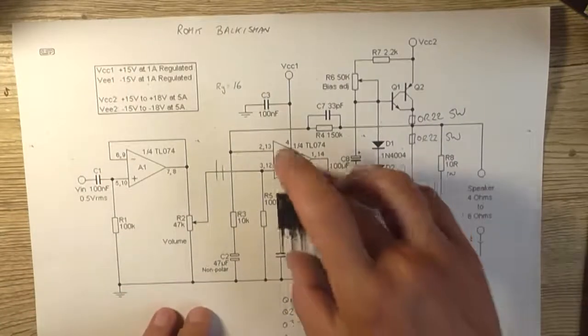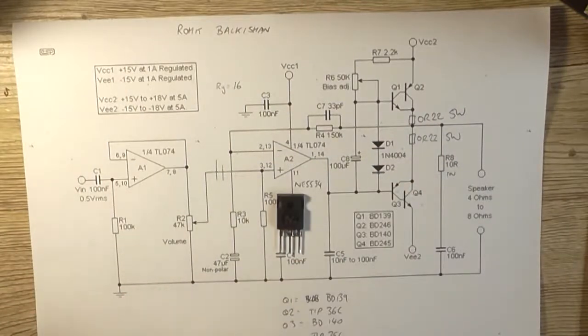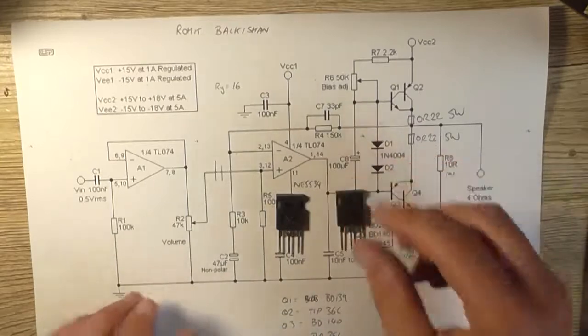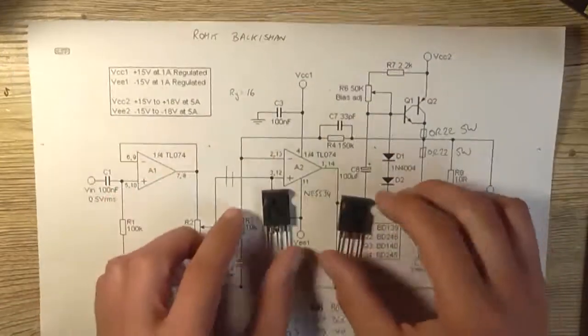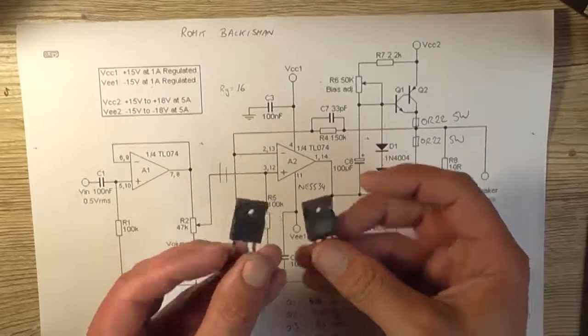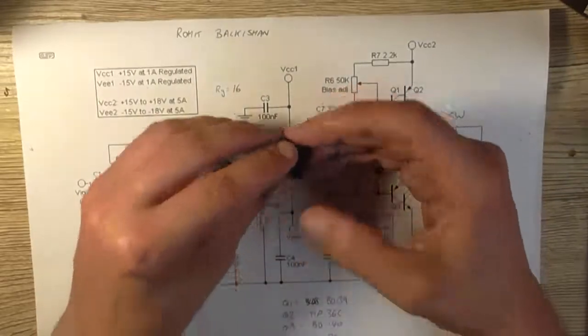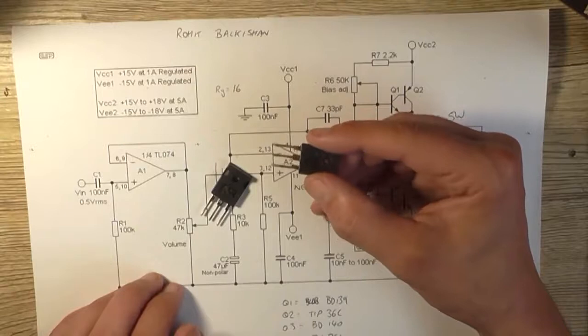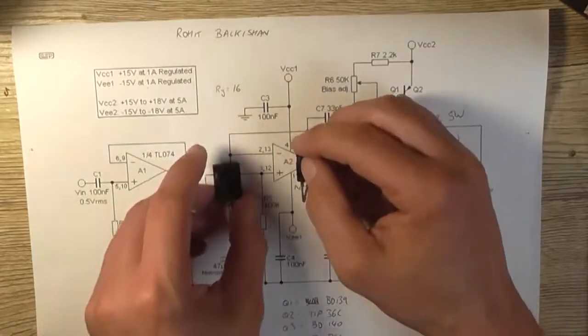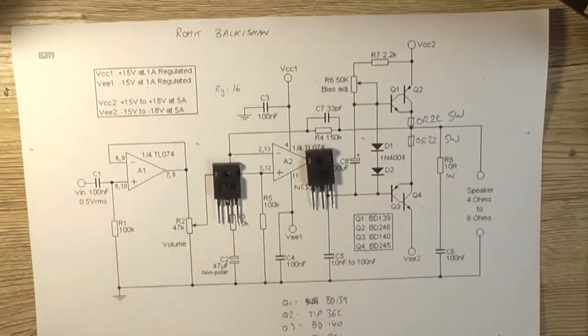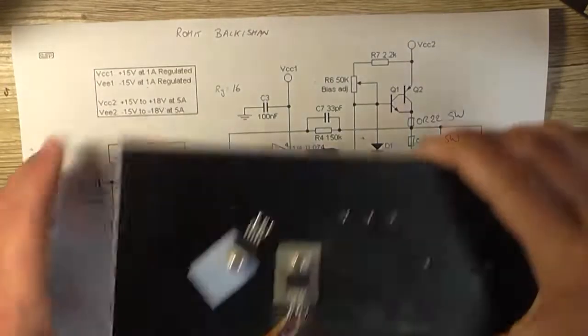But here's our output transistors. That's the TIP35C. That's another TIP35C and TIP36C. And they're just flat pack transistors, power transistors. But because the lead thickness is so thick, it's not going to fit in the socket board. So what we'll do is I'll assemble the output stage in dead bug style. That is, everything will mount to this heatsink here,